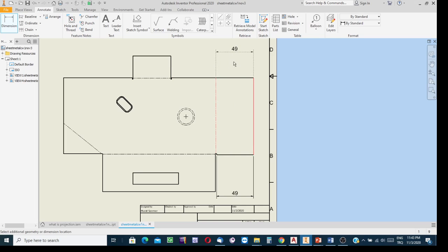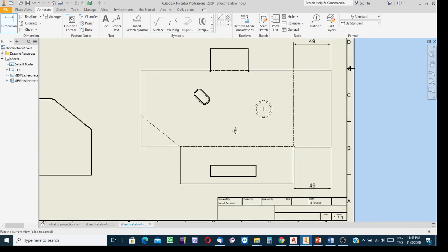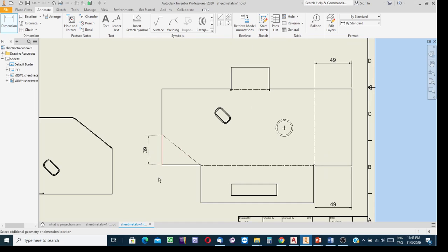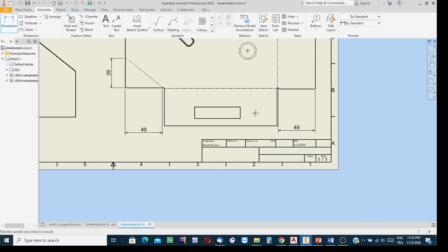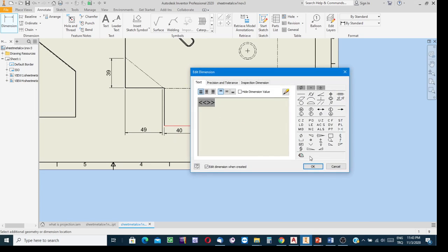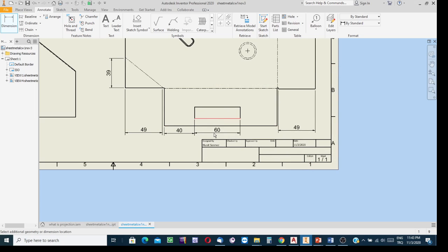And also, well, this dimension is to be shown. Okay, well, it is to say that mark the path along which this part is to be bended relative to here, measuring 49 millimeters. Okay, and show these coordinate values. Okay, to locate the terminal points of this path along which this corner of the object sheet metal will be bended. Okay, and the location dimension for this cutting relative to here, for instance, show this dimension. And then the size of this cutting,